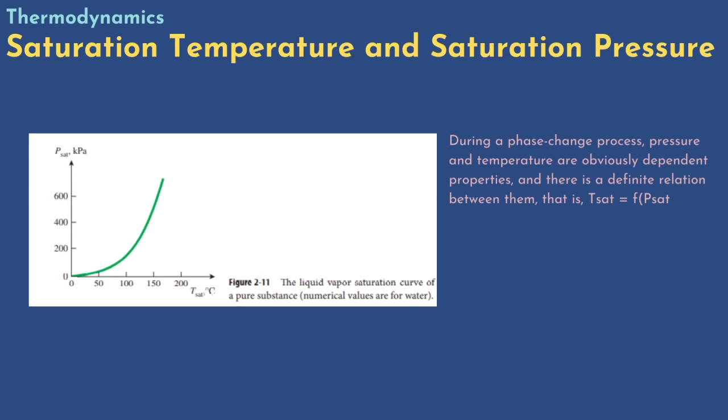The atmospheric pressure, and thus the boiling temperature of water, decreases with elevation. Therefore, it takes longer to cook at higher altitudes than it does at sea level, unless a pressure cooker is used. For example, the standard atmospheric pressure at an elevation of 2,000 meters is 79.50 kilopascal, which corresponds to a boiling temperature of 93.3 degrees Celsius, as opposed to 100 degrees Celsius at sea level. For each 1,000 meters increase in elevation, the boiling temperature drops by a little over 3 degrees Celsius.